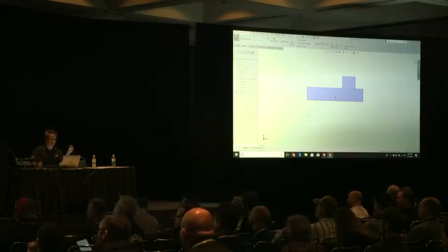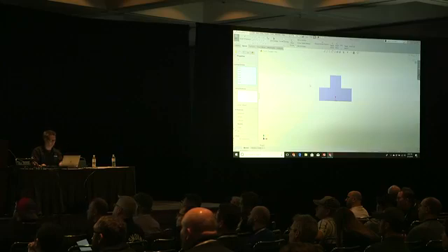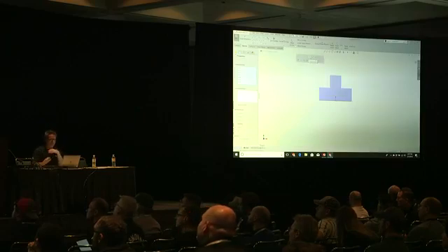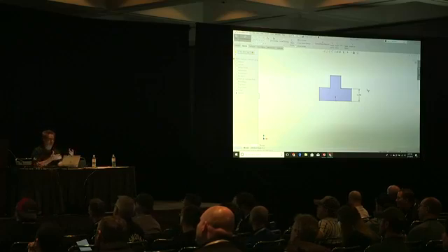All I did here was I started with a midpoint, and then I got the rough shape. Well, if I do a crossing window and make all those equal, and I'm going to undo that because I want to show you something else. Make all those equal. Don't move your mouse. There's your smart dimension. I can come right over. One dimension, I have a fully defined sketch. And I sketched that really sloppy, you saw.